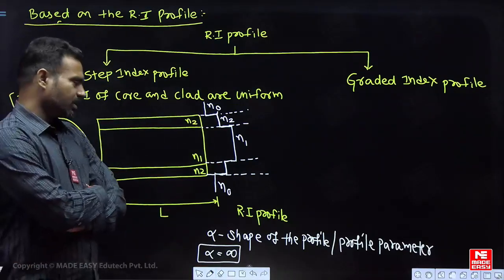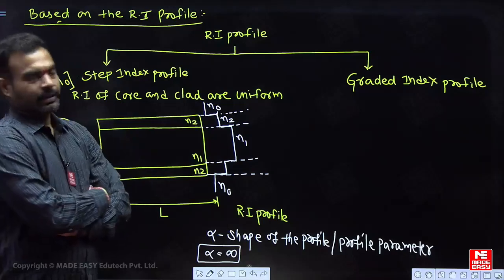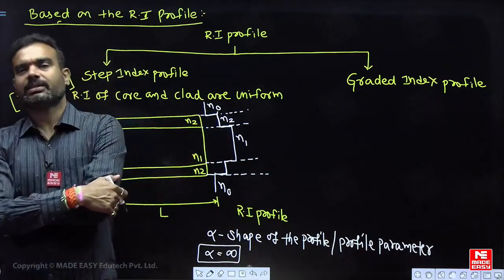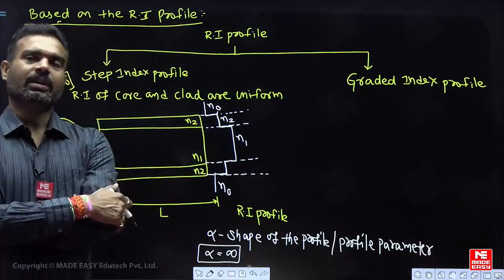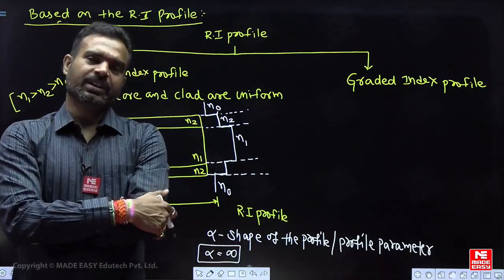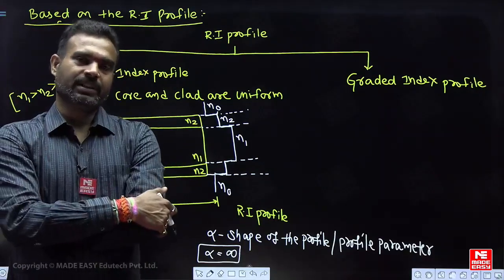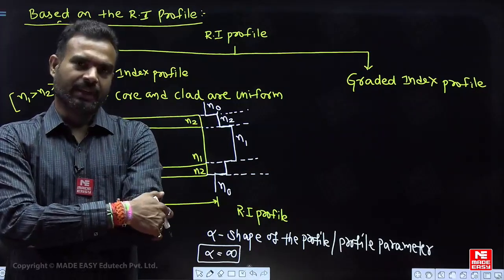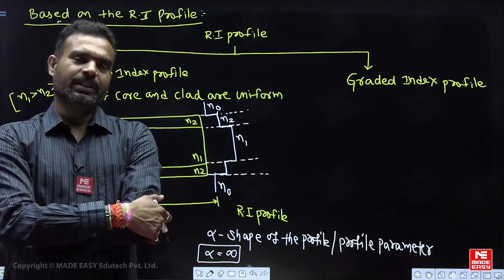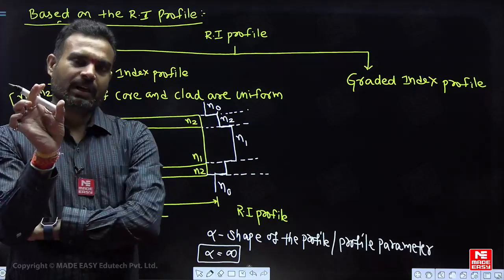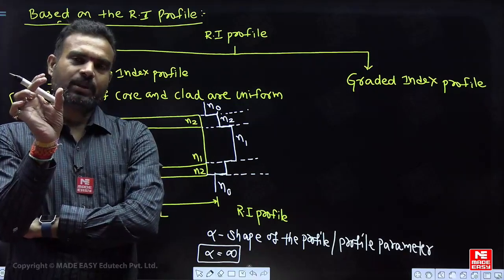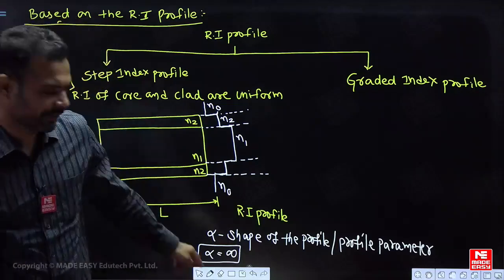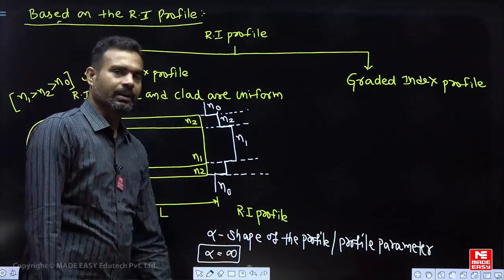But now just try to understand a simple point here. So, a step signal. If you differentiate a step signal, every time you get an impulse. You studied this in signals and systems also. du(t)/dt is equal to delta(t). When you differentiate the step signal, we get an impulse signal. The magnitude of the impulse is infinite, and that's why here alpha is equal to infinite.